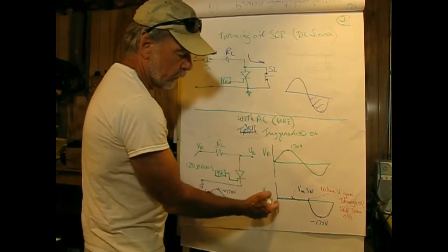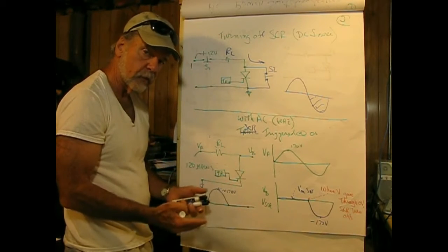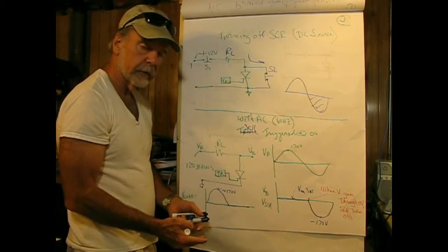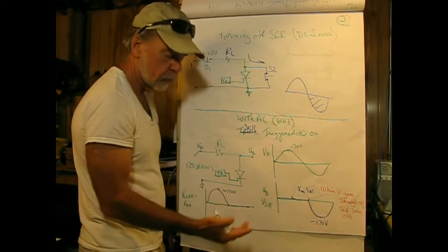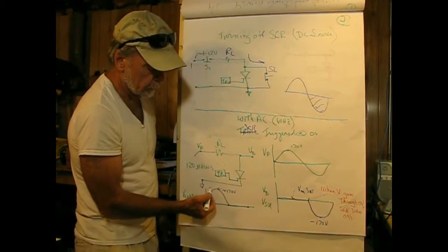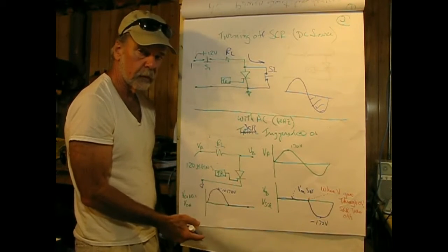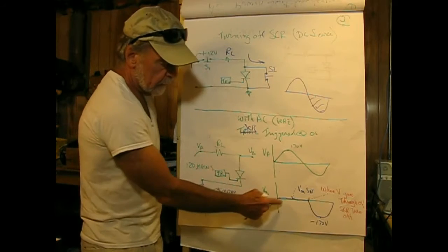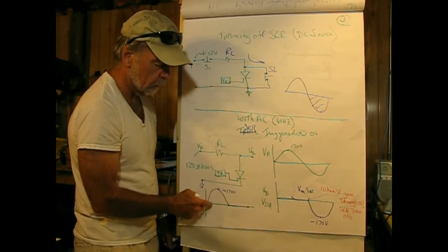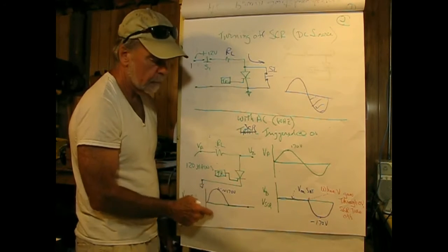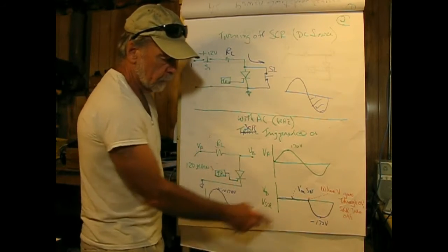So what we need to think about then is this is basically an active load device as is the way it's wired. Now let's take a look at the load voltage. Well, if there's no voltage across the SCR essentially when it's turned on, the load voltage varies up to approximately 170 volts, which is the peak of 120. So the instantaneous value at any point of the voltage across the SCR and the load voltage have to be equal to the input voltage. And I'm thinking about 1.6 volts for saturation on this.